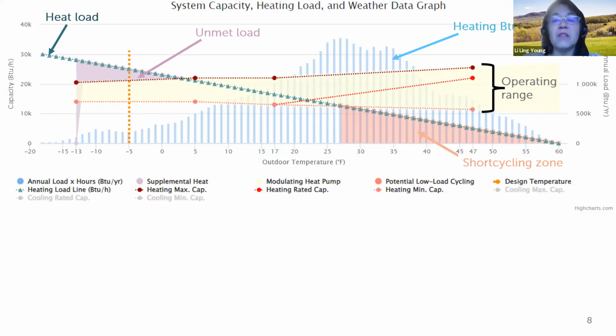So you can see that there's a big bulge of heating consumption in the warmer temperatures. And remember what I said in that first slide, it's not that cold here for most of the season. 80% of the season is at 20 degrees and above. And so 80% of all of this energy is being consumed. It's more than, yeah, maybe it is 80%. I'm going to back off from what I was about to say. But in any case, you can see that most of the energy in the heating season is expended in these warmer temperatures.